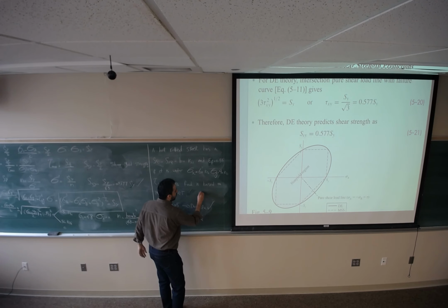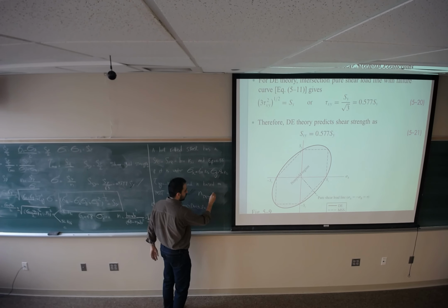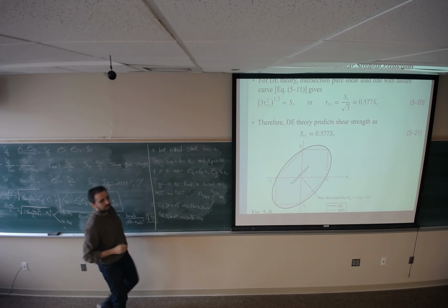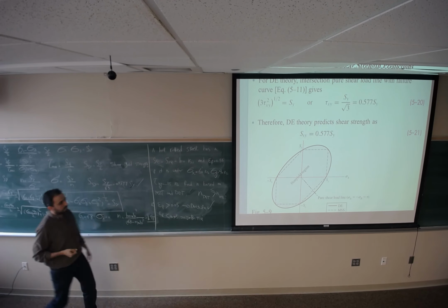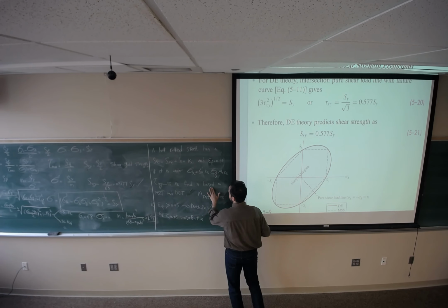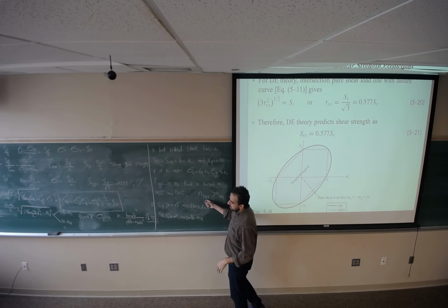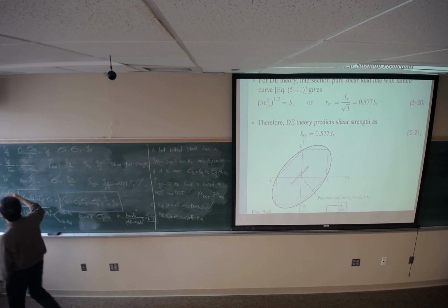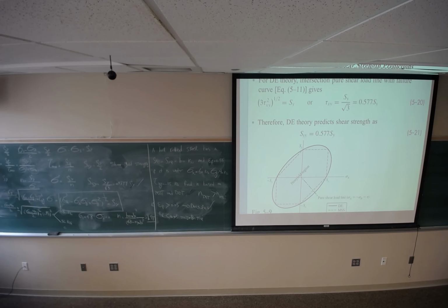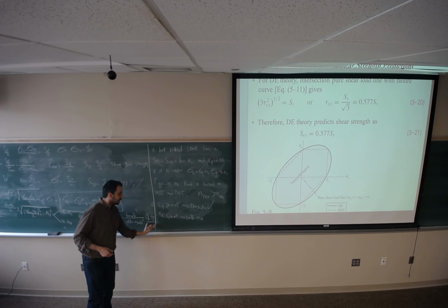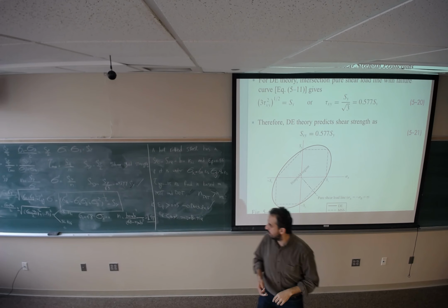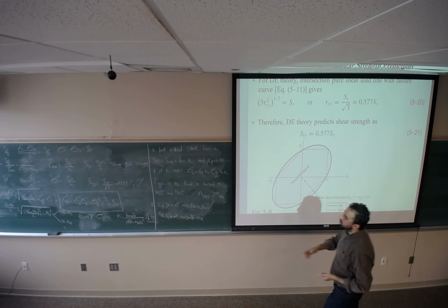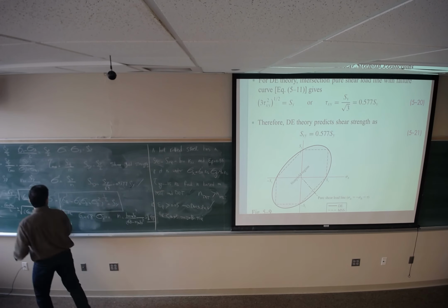For DET, it should be greater, and for maximum shear stress theory, less. We expect to get the greater value because this theory is less conservative than maximum shear stress theory. So the factor of safety for the more conservative method should be less than the factor of safety for the less conservative method, which is the distortion energy method.